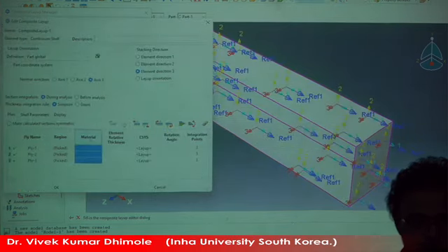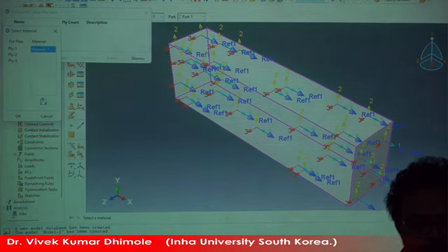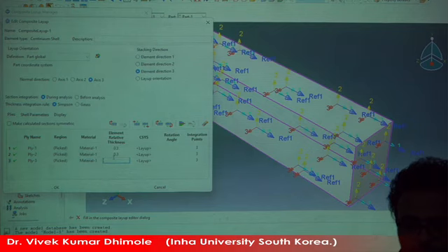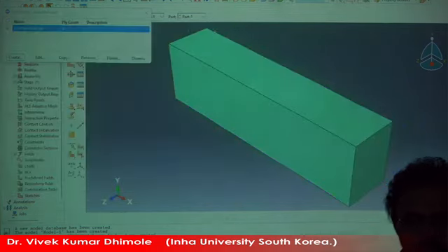Material, let's see, one simple for each. You can change the material for every ply here, but we are deciding only one material. Element relative thickness on the element basis, so we are just taking 0.3, 0.3, the length of the element divided by the thickness of that body. And the rotation angle, let's decide 0, 45, 90. And the integration point means inside the element, the integration point. We are not choosing any symmetry right now, but let's see later on. First here, and we can see what we decided.